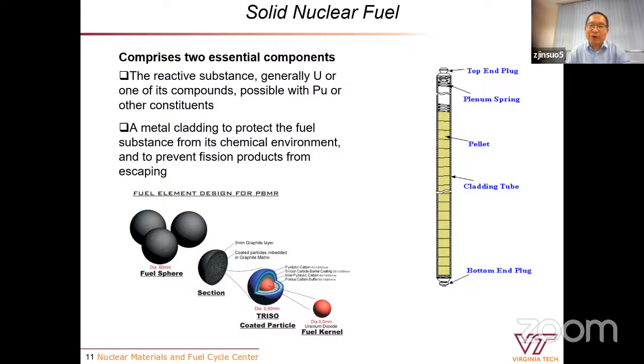And for the fuel rod, we do not have that issue. The cladding is very thin. However, you still need to fabricate it, and you also need to think about the corrosion of the cladding by the fuel as well as by the coolant. The fuel has an interaction with the cladding, and the coolant also has an interaction with the cladding. So normally we have to change the fuel rod from the reactor after some time. One of the reasons is the corrosion of the cladding.